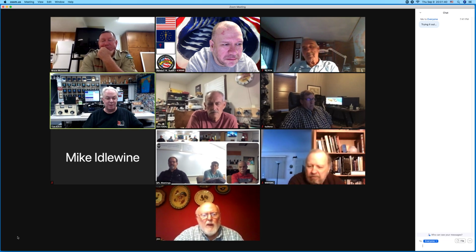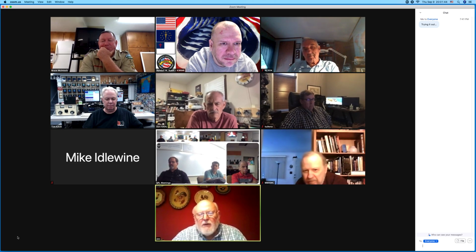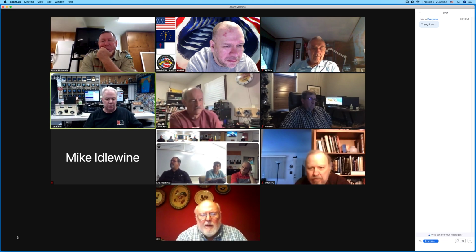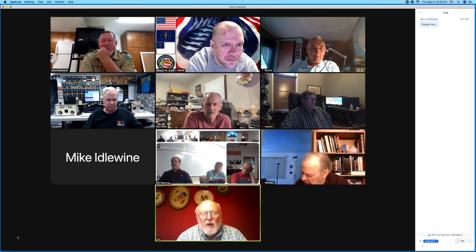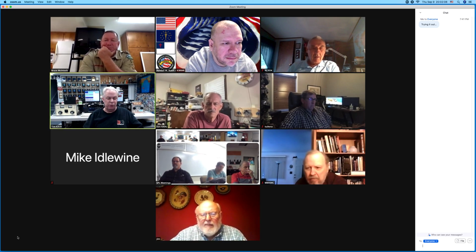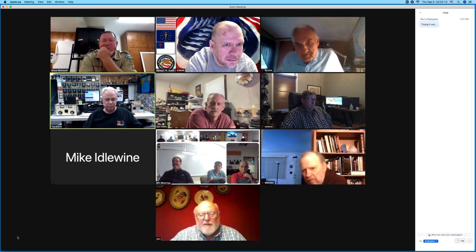Any other questions? Can you show that slide of the tower grounding situation again with at least 3 ground rods? Yeah, so those are 30-foot radials, and there are 3 ground rods equally spaced on that 30-foot radial, and then there's a ring around the tower. Okay, so there's a total of 9 ground rods on the tower itself. Yes. How deep? 5 foot, 8 foot? I like 8-footers, but if 4 foot is what you can get, that's good too. Okay. Thanks.